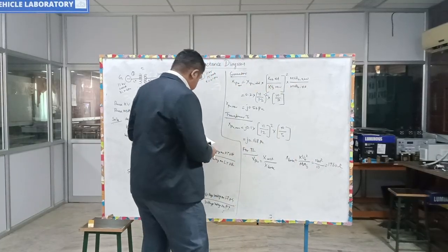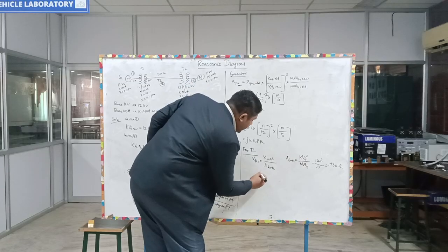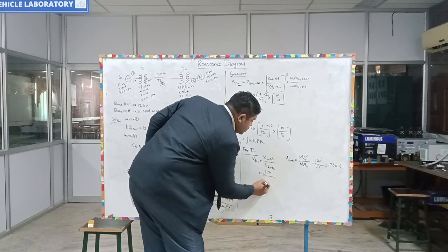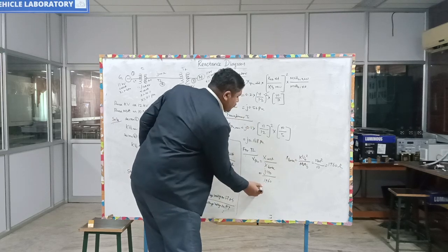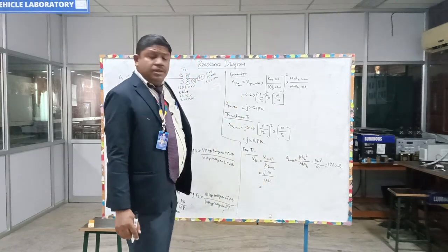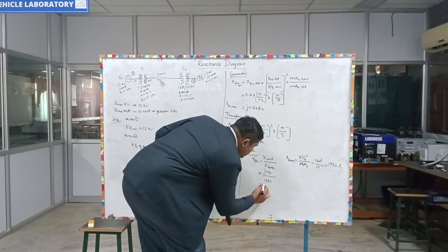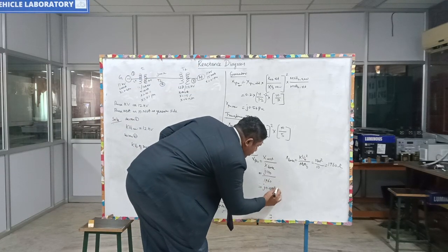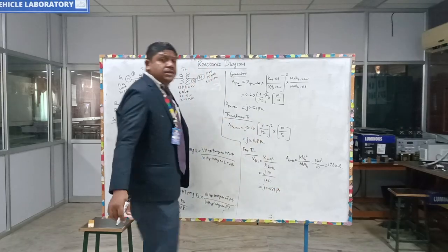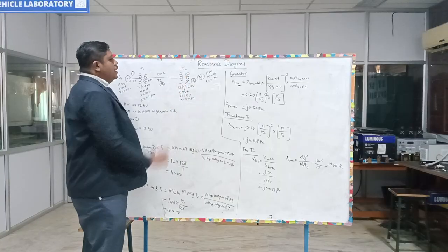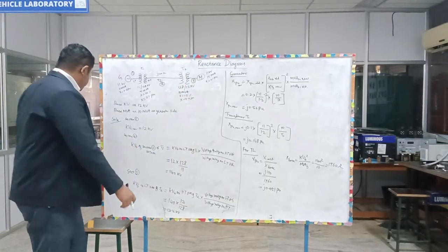So now substitute here, actual value is j100 divided by base value 1960. So for the transmission line, the value is j0.051 per unit. So the unit is per unit.